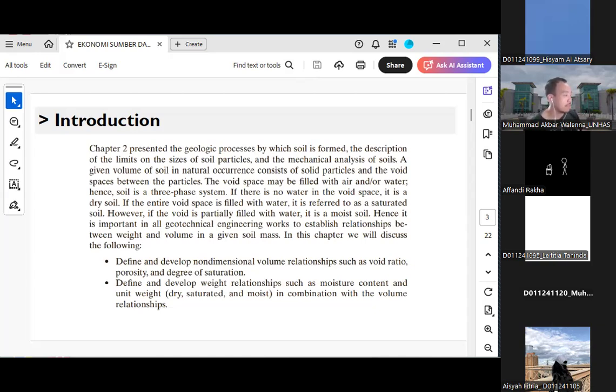When it comes to compressibility, soil is going to be much more compressible, experiencing more deformation or settlement, when it contains more water and air. This is because air and water can easily be compressed, squeezed out of the soil three-phase system, or mobilized through the application of loading.